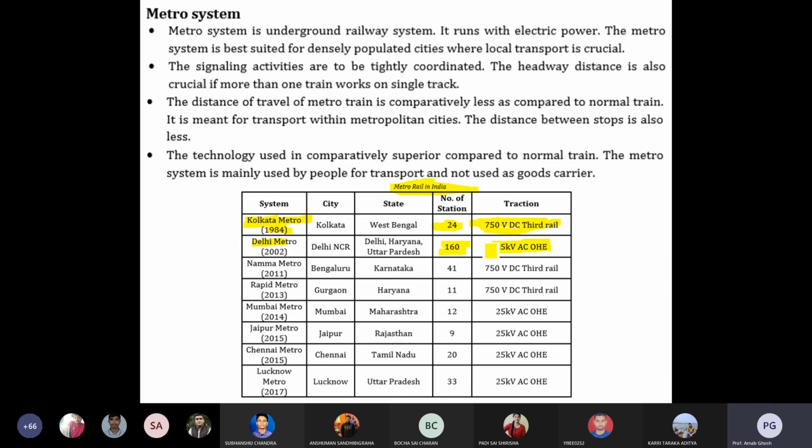Normally if you travel from one place to another, you can see along your railway track some substations that are 132 kV/25 kV. That is known as a traction substation. What does the traction substation do? You are giving the supply to the feeder. Suppose you have two lines, after some duration you have to give the power to those lines, the catenary and contact wires. You have to give that power supply to the catenary wire, not the contact wire.